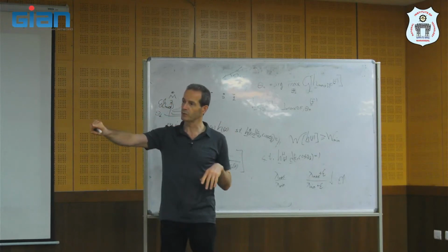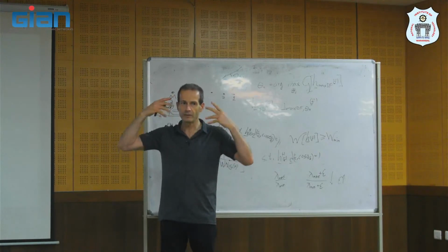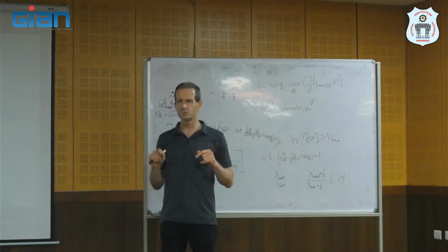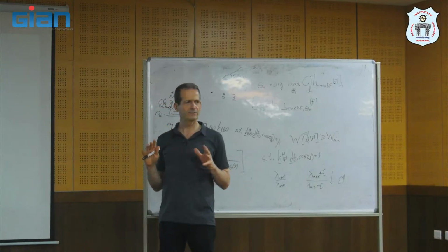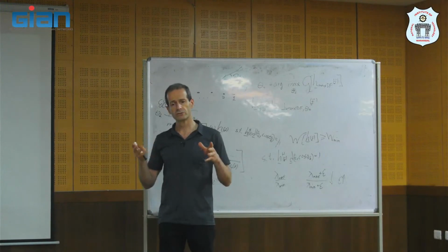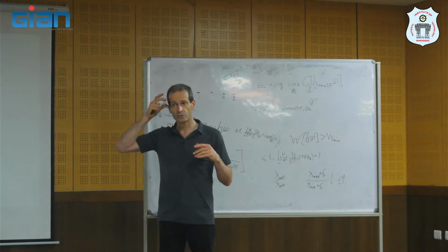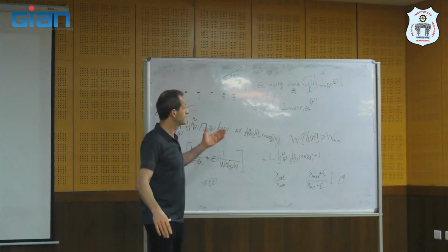Remember that sometimes when they increase the volume, you hear howling or very loud noise because of the feedback. This is very disturbing, especially for hearing aids. So if we want to reduce that feedback, we add a null on the beamformer.